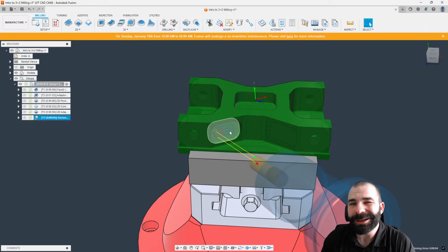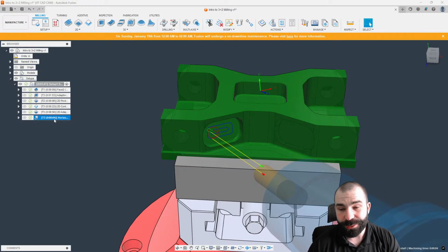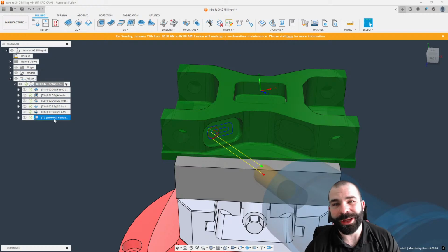But when it comes to that tool orientation, something you guys noticed is the number of different mouse clicks I had to do for orienting my axes. Now, that would be a pain if I had to do this across a couple of toolpaths. But did you know, you guys will have to tell me in chat, that you could actually use joint origins to control your tool orientation?